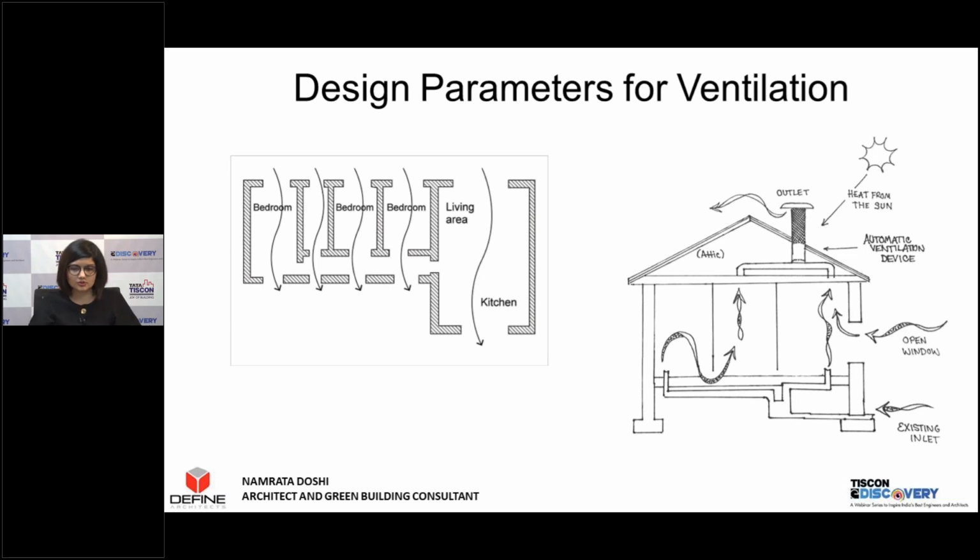Again, a couple of sketches for those of you who are more interested in studying the subject on how the window openings and door openings should be placed. Cross ventilation is the best strategy, very simple and direct, having openings on either sides. Like I said, keep one bigger, one smaller. That enhances pressure difference and helps you in ventilation.